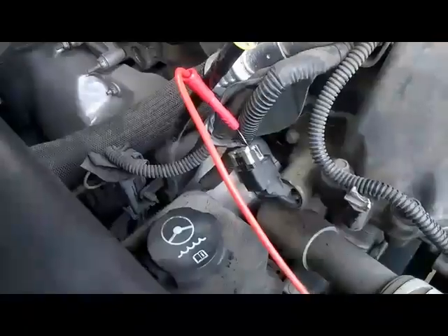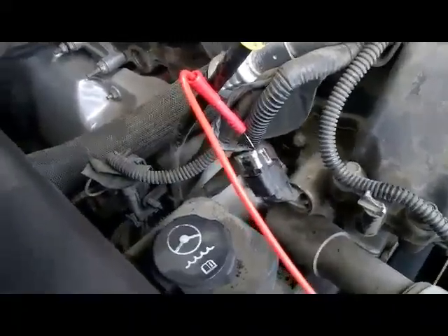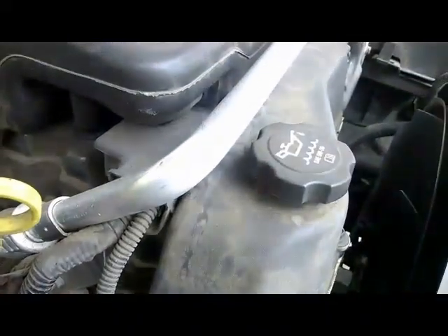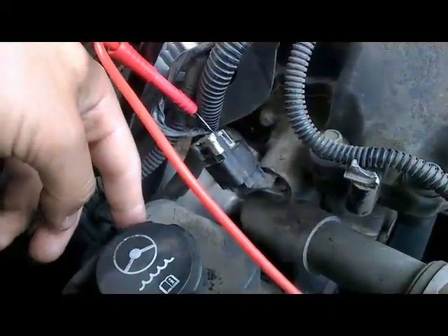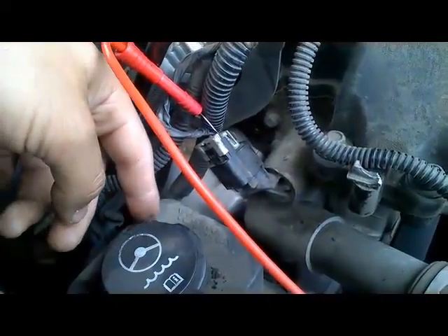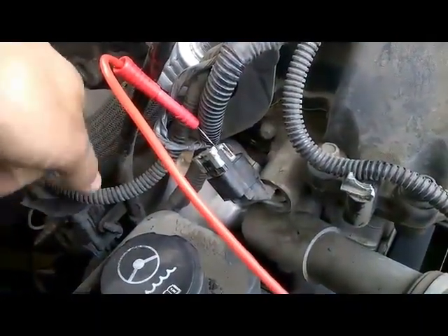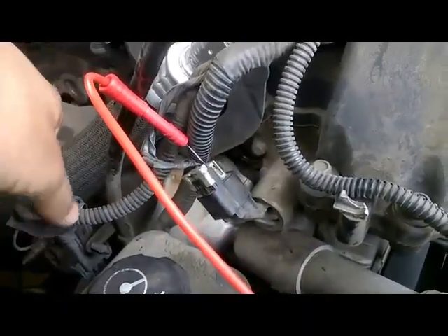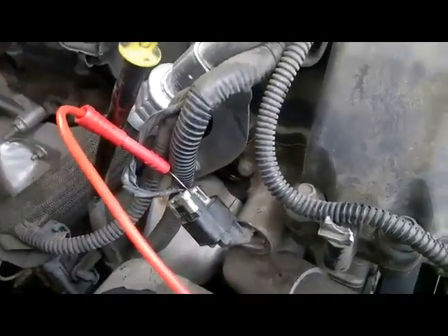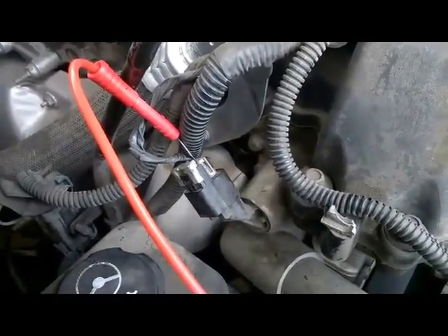All right, guys. So this is where the camshaft actuator solenoid lives. It lives near the oil cap, which is also next to the power steering reservoir. This solenoid is a 2-wire, in which we confirm is a brown wire and a black wire. Our brown wire is a 12-volt source feed, and our black wire is our low reference, which is our ground wire. So currently, I have the key on with the engine off.